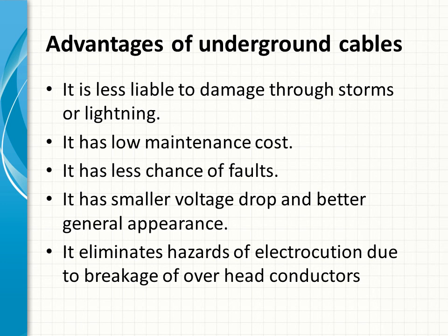Then it eliminates hazards of electrocution due to breakage of overhead conductors. This means that by laying them underground, it's rare to be tampered with by an individual, as compared with the overhead transmission, where somebody can climb up the pole and try to interfere with the conductors, or maybe a tree falls, cutting the conductor, thereby exposing individuals to electrocution.